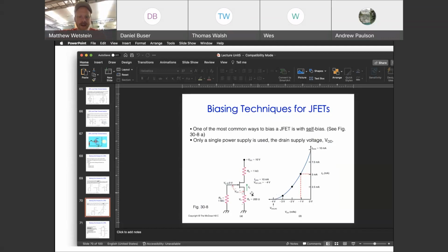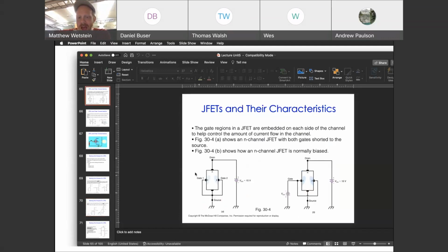That depends on the particular choice of material, but the operative point is that if you think of the gate source as a PN diode, the condition under which you will choke off the current is where you are reverse biasing the diode, because as you recall, reverse biasing a diode expands the depletion zone. To forward bias a PN junction, you would apply positive to P, and you can see here we're applying negative to P, and positive, or at least less negative, to the source. That's the key to how to bias these.